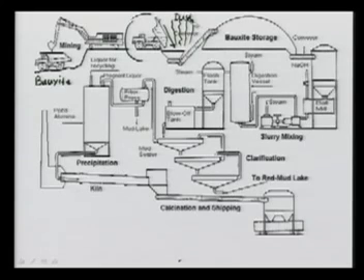Let me make it a little better here. So here you have the emissions, and the emissions are that of dust or particulate emission. There are various ways to handle the dust emissions. Either you can provide fogging nozzles, or you can have a little moisture content in there, or in fact you can enclose the entire area so that no dust comes out from there.